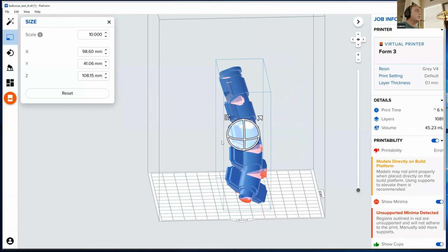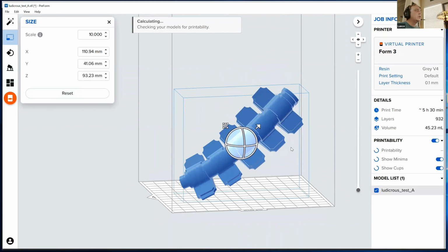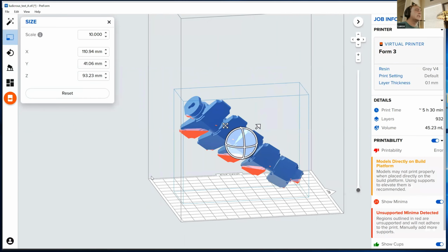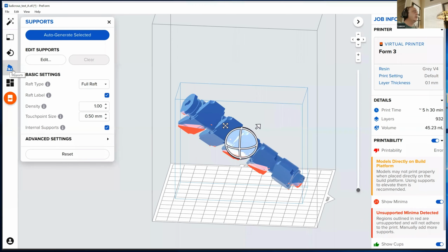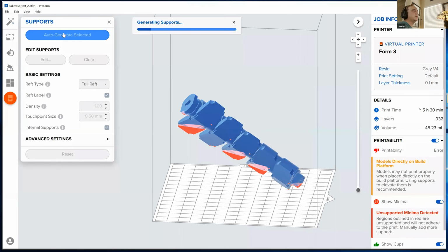Now, another thing is when you're doing 3D printing with SLA printing, you want to make sure that you're kind of building like a stalactite. You want it to build off a support because it will actually be anchored to a platform. In fact, this platform is this grid right here, but that will be upside down. Imagine this whole thing dipped upside down and inverted. That will now be hanging, and you'll have an anchorage here, and this will be grown suspended below it. Now, to do a really quick example of what the supports are, I'm just going to go to this little thing called supports, and I'll just auto-generate some supports.